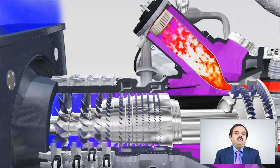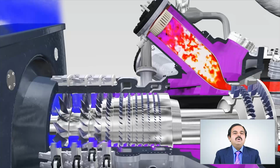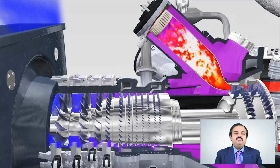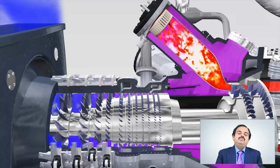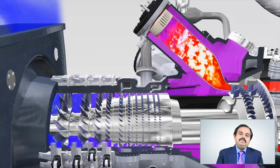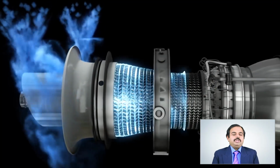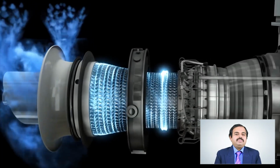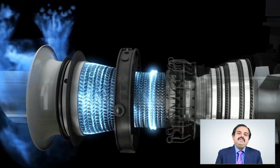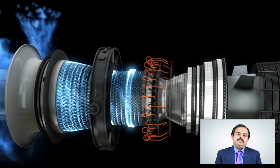The ability to resist hot spot temperatures and give long life demands that hydro-finished base stocks are used which respond to antioxidants. The step-down gearing needs protection from anti-wear and extreme pressure additives which protect but at the same time prevent attack on yellow metals.